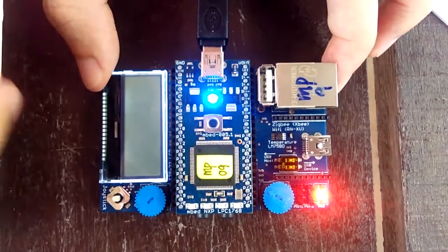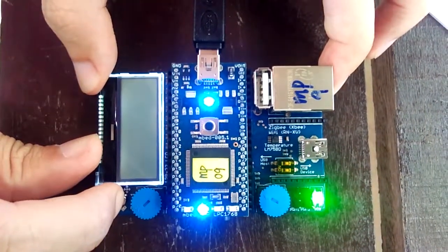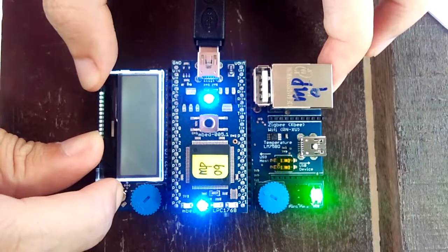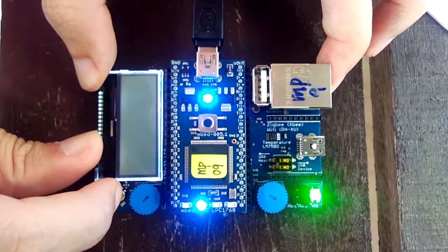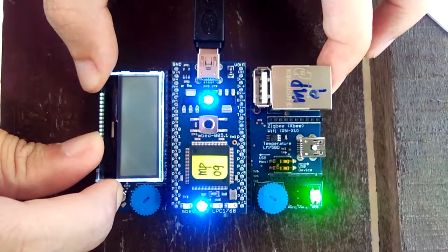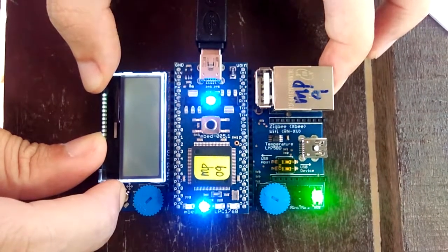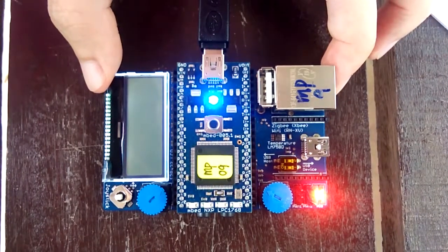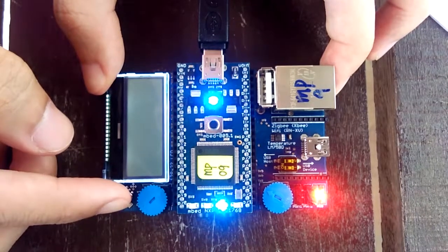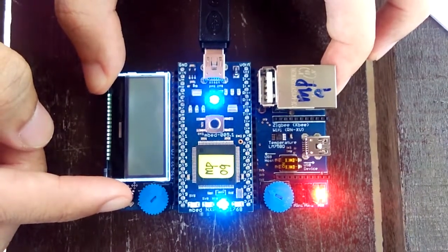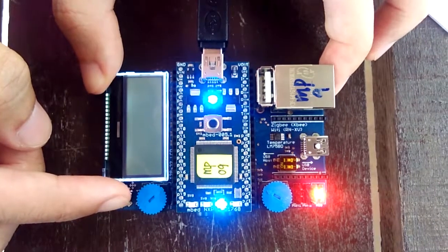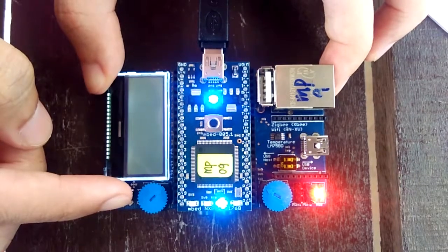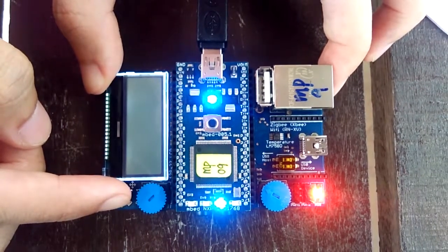So, when the down button is pressed, the output occurs at P1.20. Once the temperature sensor detects the low temperature in washroom, the red light will change to green light. Thus, the water heater will be turned on automatically. Next, come to the left button. When the left button is pressed, the output appears at P1.21. According to this situation, the automatic flush system is activated once the IR sensor has detected the person before and after leaving the toilet seat.